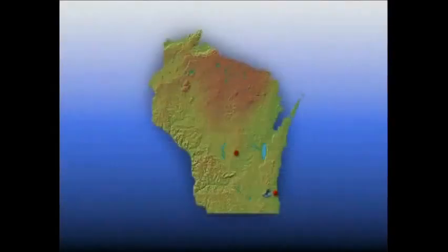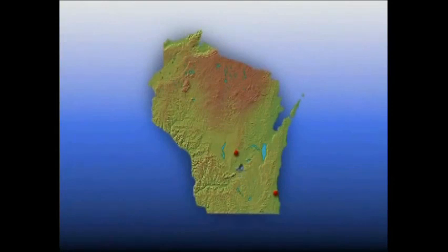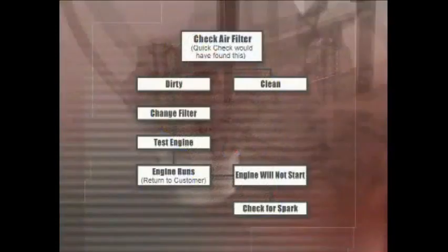It's similar to using a road map, because each time you come to an intersection, you have to decide where to go next. With a flowchart, you base your decisions on the diagnostic tools, your own experience, or advice from a more experienced technician. From here on in, we'll use our carburetor symptoms to build a detailed carburetor diagnostics flowchart which should make solving future carburetor problems easy.